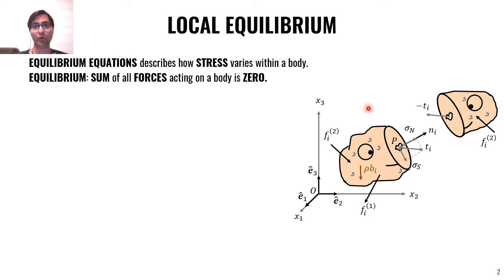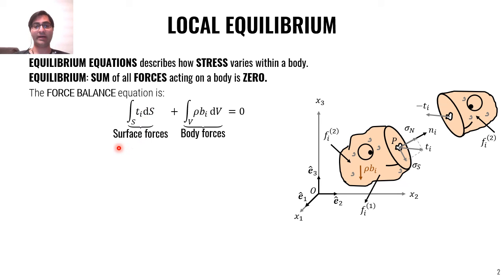It doesn't explode or shrink or expand or whatever. It stays as it is. The force balance equation is written as surface forces plus body forces becomes zero. For surface forces, we have the traction multiplied by ds integrated over S. For body forces, we have density, body forces multiplied by the volume integrated over the entire volume.